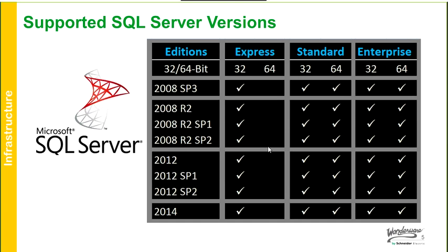Since InTouch 2014 R2, when you run modern applications, you also need to install a SQL server. And if you don't have one, then the system will install an Express version for you. And the editions we support so far is SQL 2008 Service Pack 3 and up to the latest version of SQL, that is the 2014 release. We're supporting both the 32 and 64-bit versions, except when it comes to the Express. Then it's just the 32-bit version that is supported.